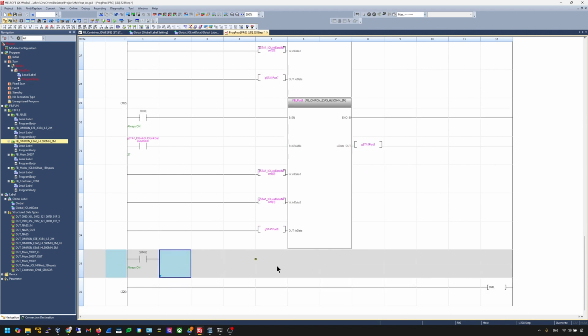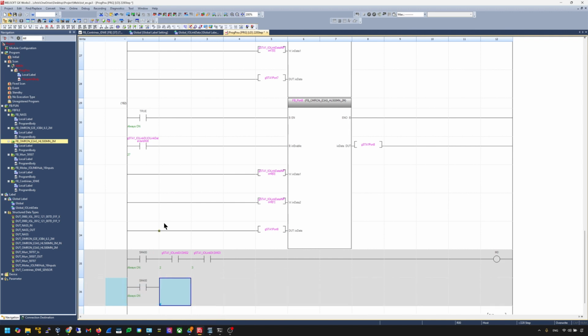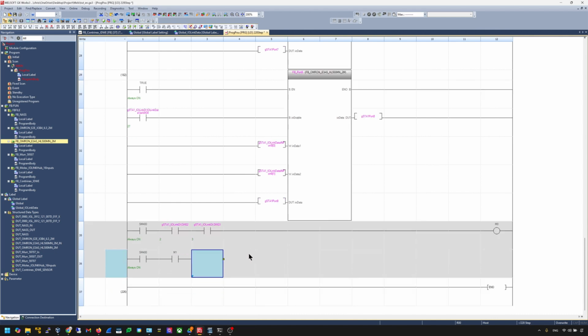SM400 is always on, and then GSTA, you use the DI dot the second one, okay, and then I have the first one, and this is the coil, so I put the coil in here, okay, and then just put M0, great, and then SM400, and then M1, other bit.